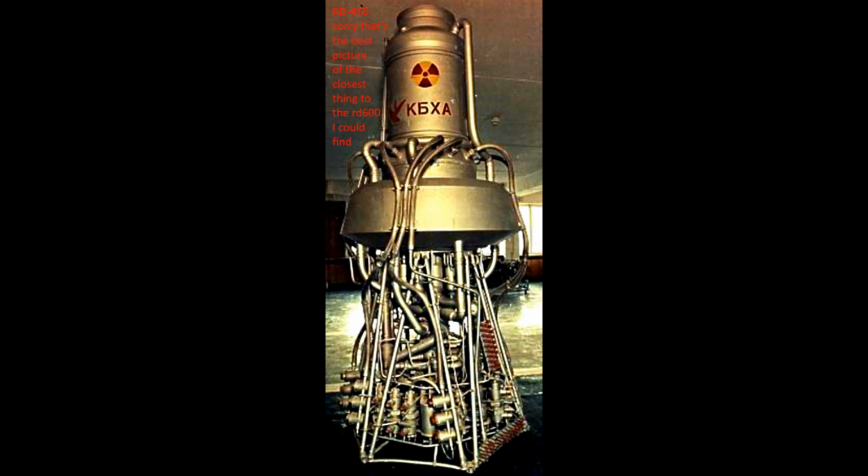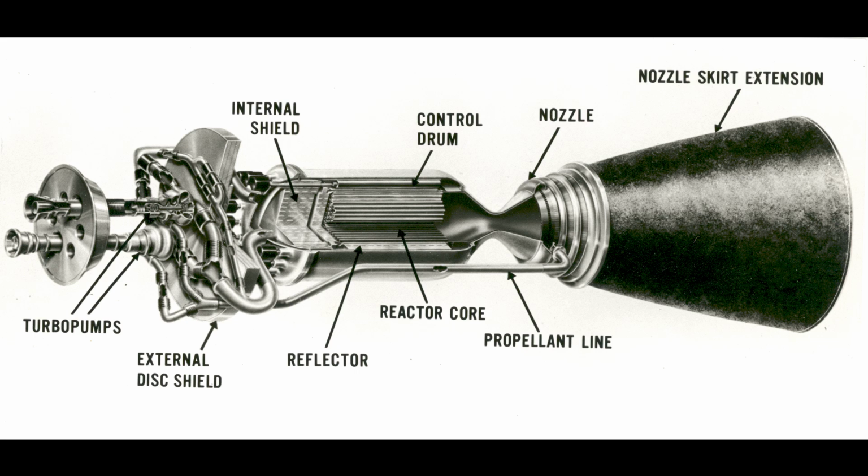There's no real combustion there, though it can be combined with a combustion, but you have a chamber, propellant is heated up in that chamber, it goes out through a nozzle and accelerates. Just instead of using a chemical reaction to heat it up, you use a nuclear reactor core that is suspended within or nearby the reaction chamber, and connected so that heat can easily flow.